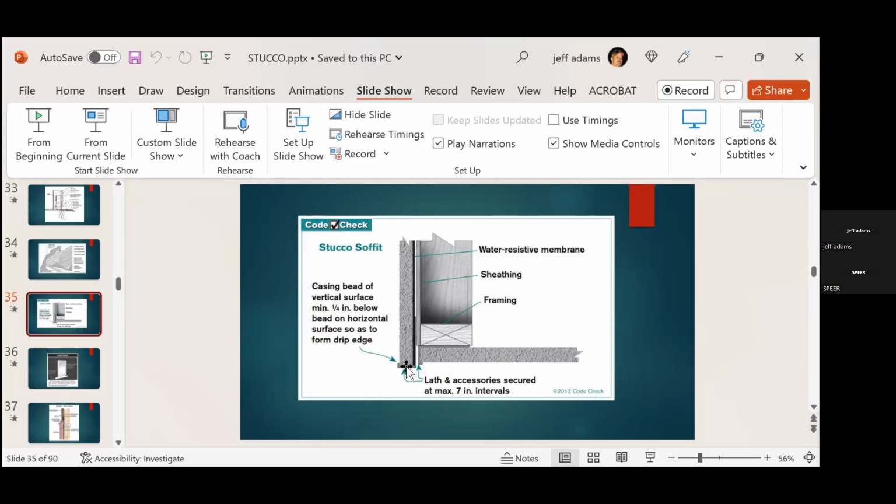We overhang a 1/4 of an inch. Yeah, there it is, a 1/4 of an inch below. This keeps this drainage plane open. So whenever you see a soffit, or say this may be our porch beams, our double LVLs for porches, they're doing this as all one piece and wrapping the stucco completely around that. Huge failures. I've got several houses that are only a few years old. The porch beams are completely rotted out and failing because of all the holes in here and not having a drainage plane. We have to have that drainage plane. If we trap water, we're going to have a problem.